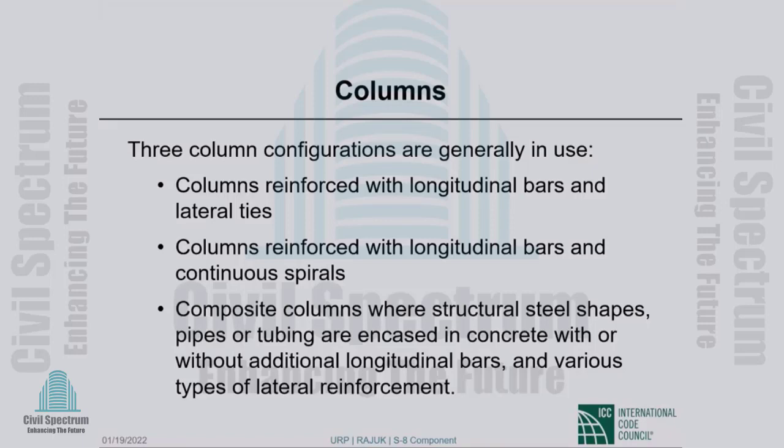I do not know definitively what the reason is. One of the reasons I speculate is, again, high seismic applications. The beam to column joint becomes very important, and we have a lot of reinforcement to place in that joint.